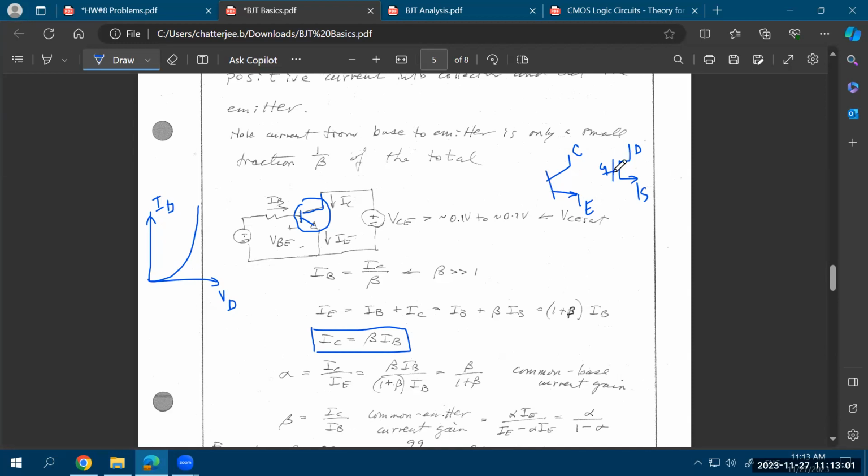The only difference for a BJT, or perhaps the biggest difference, is the base terminal, which is equivalent to the gate terminal of the NMOS transistor. The gate terminal or the base terminal is basically the control terminal. That's why you have control over the device, and that control is established using a gate voltage for an NMOS transistor. In this case, that control will be established through a base current for the BJT.